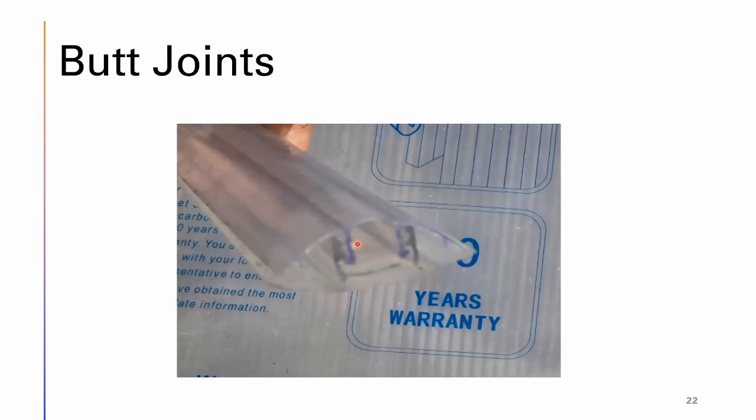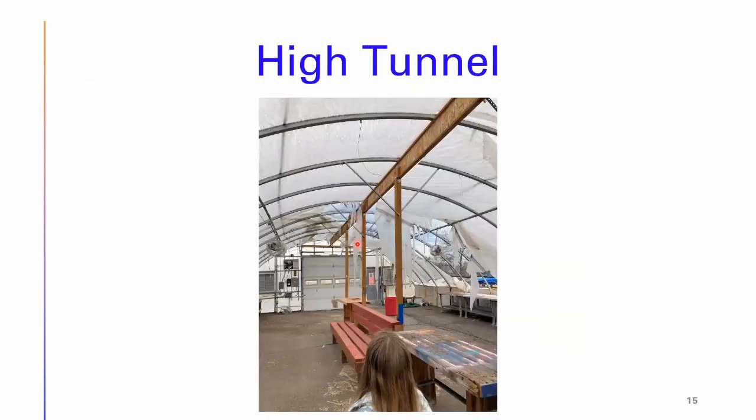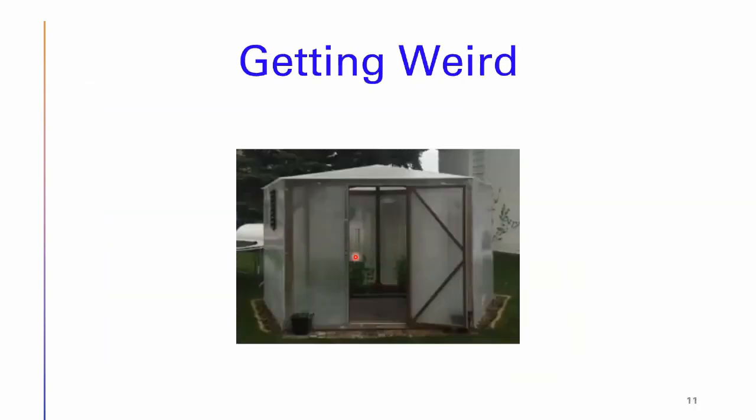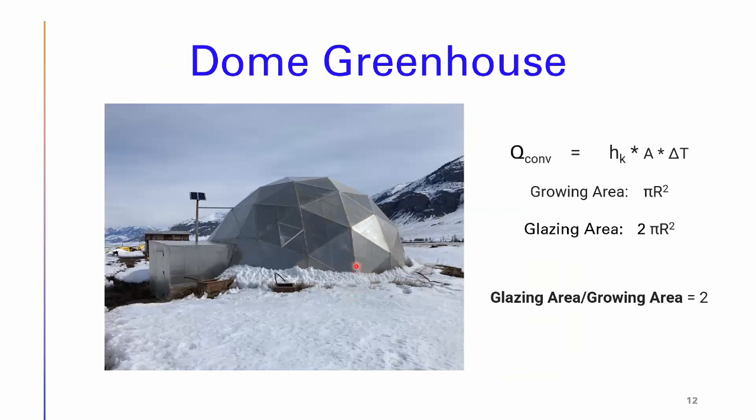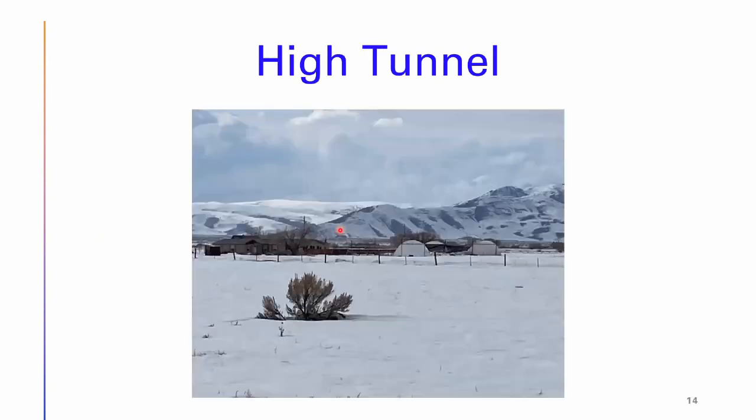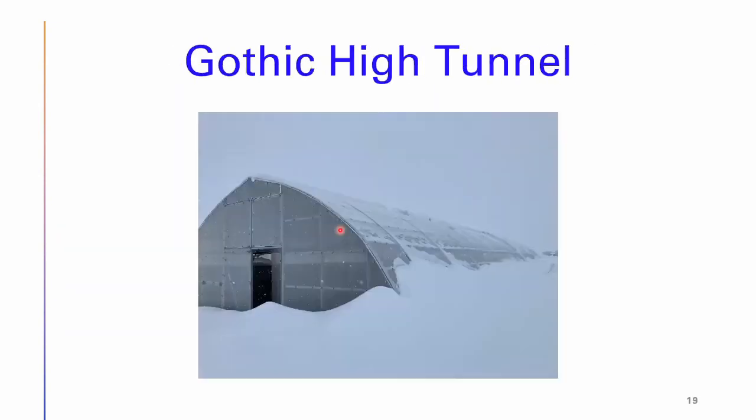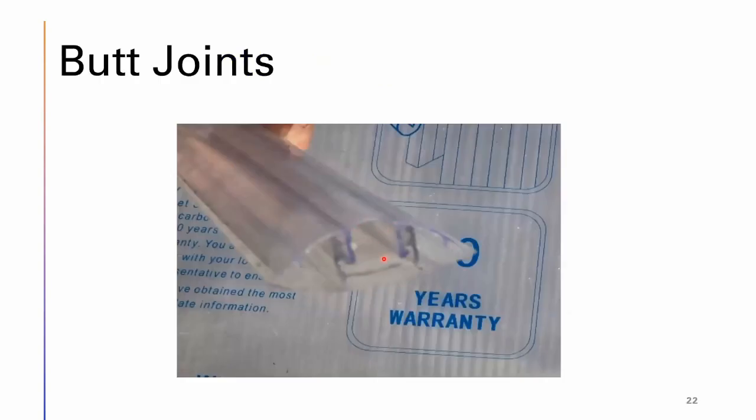It just is a 1-piece. You fit them in. It looks like an H profile. In fact, I'll show it to you. I have it on that dome. Let's go back and take a look at that dome really quick. So this is H-channel. Can't really see it up close, but the point is, it's really crazy hard to put in. And the two-part butt joint, it's just so much easier. Now it's expensive. It's $42 for a 19-foot stick versus I think it's 15 for the H channel, but it's 1,000 times worth it. I'm very happy I found this stuff and use it.